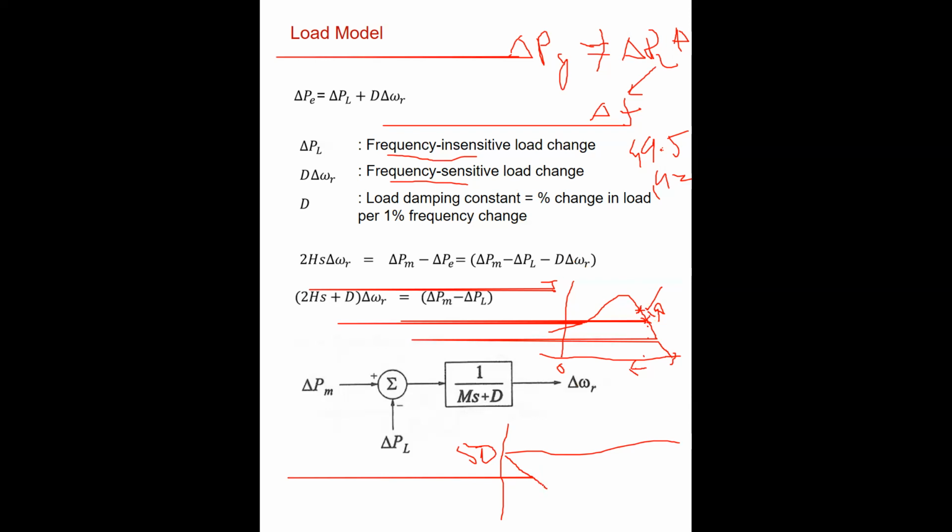So it is having a positive torque impact in the system, and thereby tries to compensate the drop in the frequency here. It is happening this way, and thus these are actually frequency sensitive loads here. So that is useful for the system, right? Yeah, that is useful for the system.